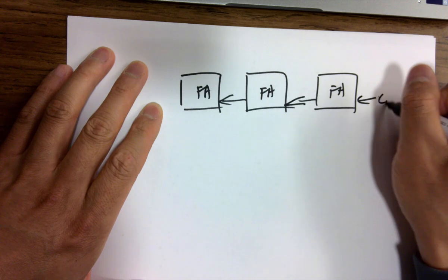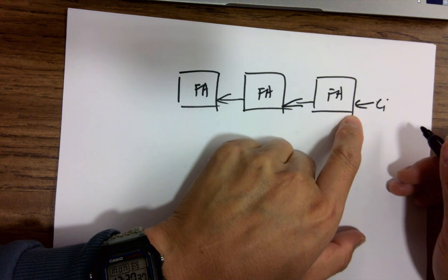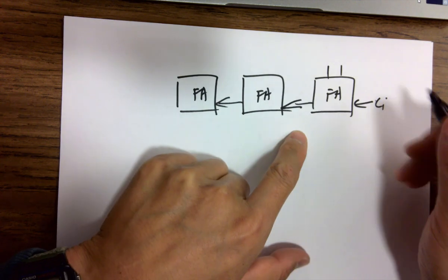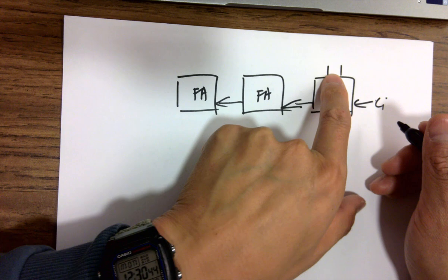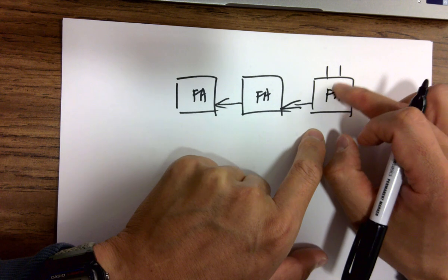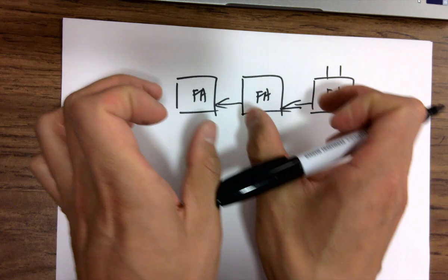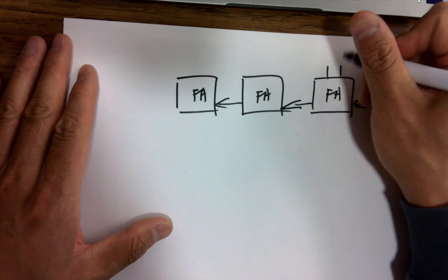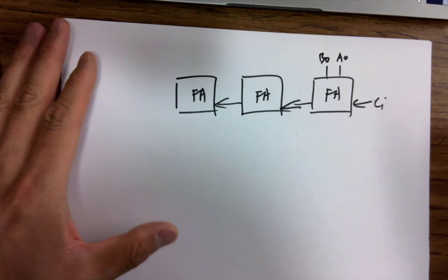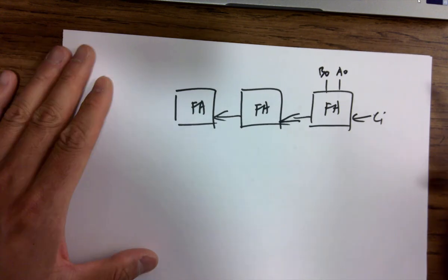These are the carries because all these adders have how many inputs? It's the 1-bit adder, right? It's just adding 1 bit. So all the sub modules are 1 bit. If you want to make it into a multiple bit adder, you just need to put multiple ones together. But all of them are just adding 1 bit to another bit, A0, B0. So how many inputs? There's a carry in, right? Carry in always. 3 inputs and 2 outputs.